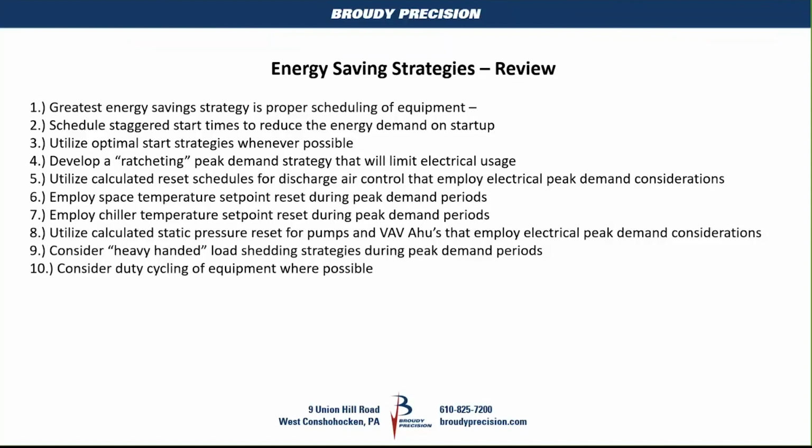Not a lot of people are doing duty cycling because it sacrifices comfort, it sacrifices equipment. You're turning equipment on and off and on and off all day long. That puts wear and tear on the equipment. Something that we need to probably discuss in the pitfalls of some of these energy saving strategies.